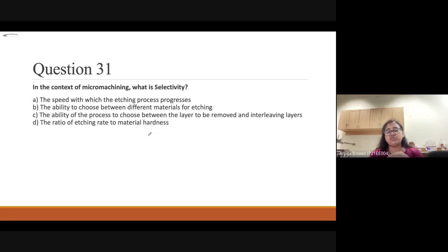If we go for the etching process, there are different types of layers present. We already discussed the KOH and TMAH solutions. Now tell me, the photoresist is present, the oxide layer is present, but only TMAH or KOH selectively etches the silicon; it does not etch the other layers. For BOE or BHF solution, it selectively etches the oxide layer, and acetone etches the photoresist.